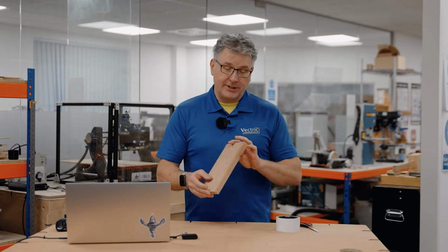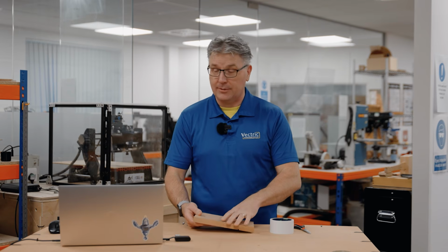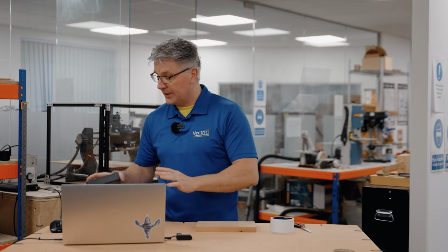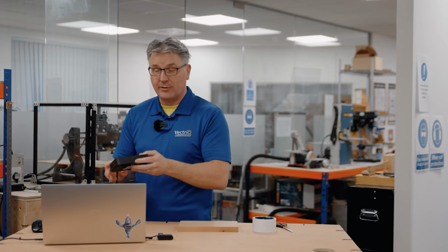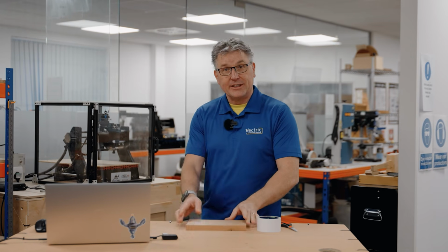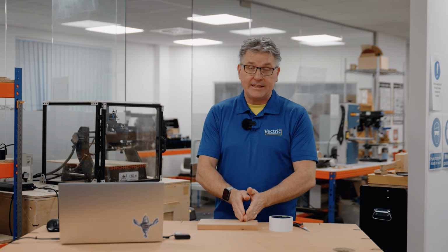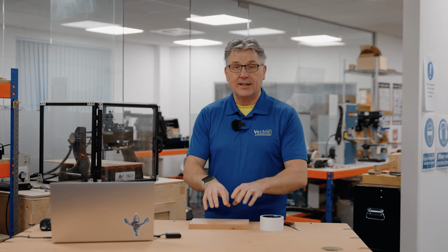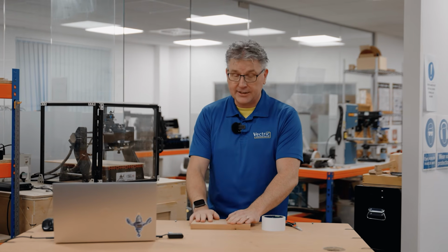So now what I'm going to do is set up my material to fixture to my CNC. And for that, I'm going to use double-sided tape this time. So once I have that all ready to go, I'm going to save off my toolpaths onto this USB drive. I can put it into this pendant that's hooked up to our Next Wave CNC, and that's where I can load my toolpaths off of to make sure they run. I'm going to fixture this or stick it to the bottom of this CNC, and then I'm going to need to go ahead and set up my datum. So my XY datum as it was in my software on this material. And then I'm going to use the touch probe to go ahead and set my Z distance of my bit off the top of my material. Again, like I did in our software. So let's go ahead and get that started.